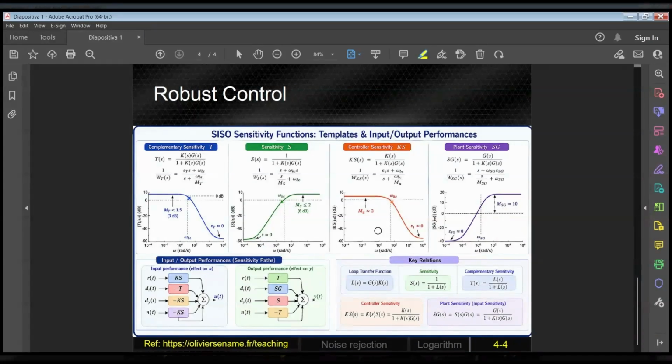If we command 300 km per hour, the actuator cannot deliver that request and saturation occurs. We usually define Umax as the maximum allowable control effort, since the control signal depends on the reference and on KS. A very large value of KS can push the actuator into saturation.